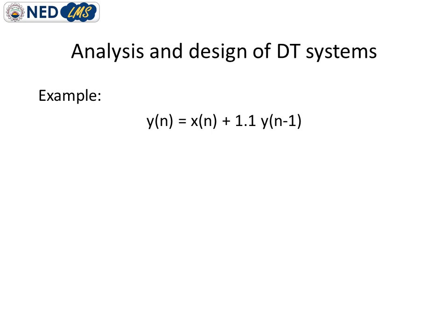As you can see in the equation, x of n is treated as input and y of n is treated as output, and there is a delayed version of y of n. This means that this system is depending upon the previous value of output, or in other words we can say that this system is having some feedback.